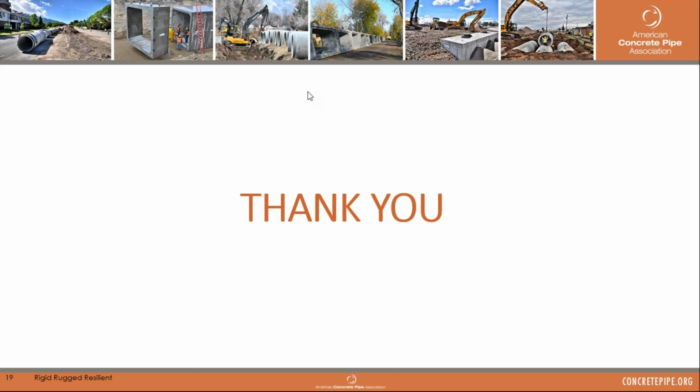Yeah, and then the other thing is just to make sure you have enough room to get compaction between those two pipe materials. Right. That would be sufficient enough for that plastic pipe. And actually, I referred to the Moser book, the buried pipe design textbook, and they cover a lot of different scenarios like that, where you have to account for possibly one pipe putting a surcharge load on the other, things like that. Yeah, especially if they're not buried at an equal level, one's higher than the other. You may see that surcharge load.